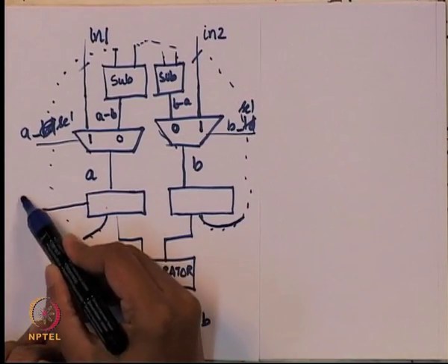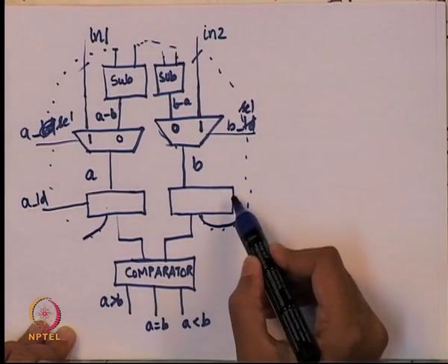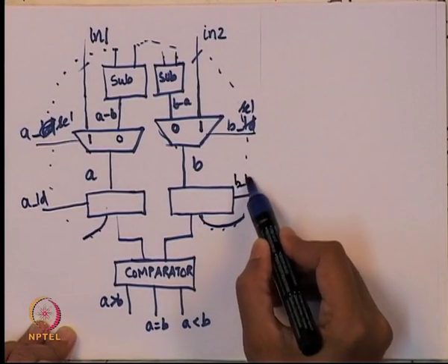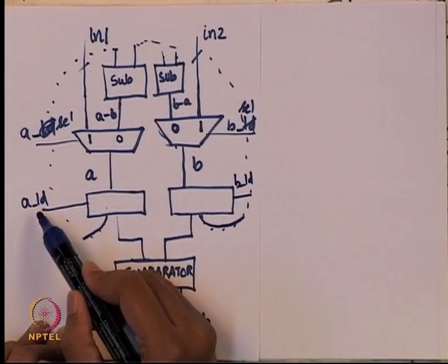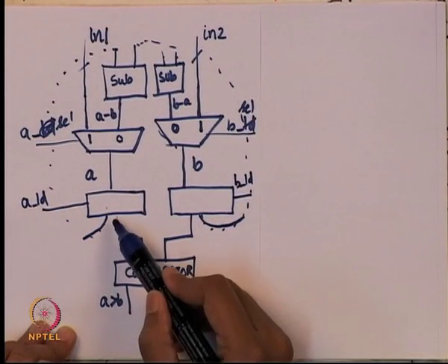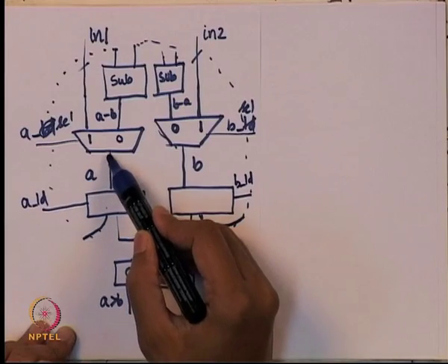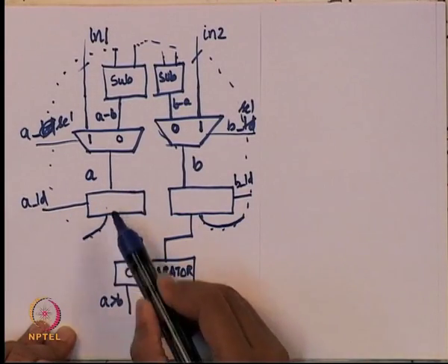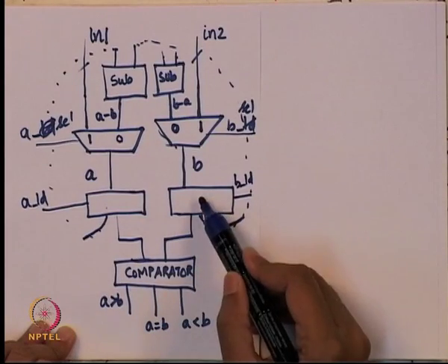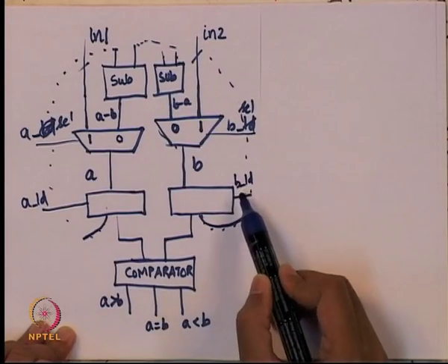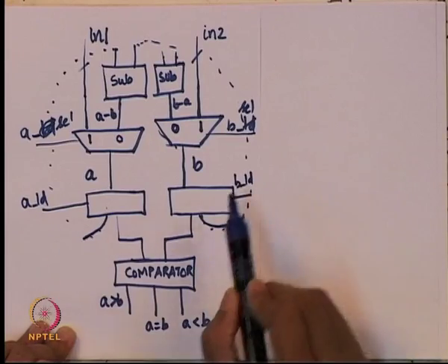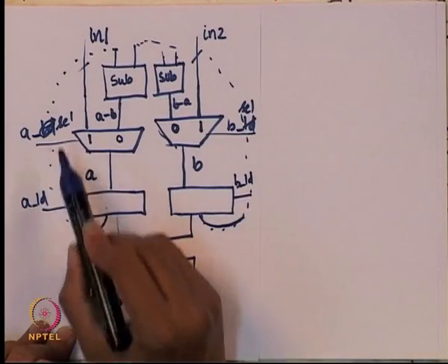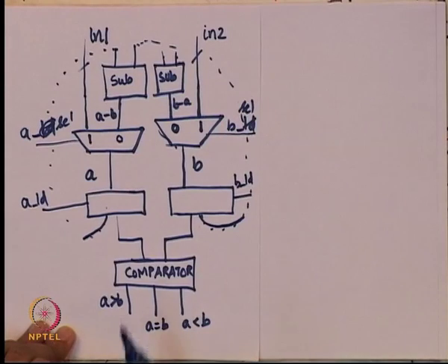So I am going to place some control on the registers on when they get loaded. When A load equals 1, the output of the A register will follow the output of the mux. If A load is equal to 0, then it will keep the old value as it is. The same thing with B. I want to use this underscore load for that signal and select for the multiplexer select. With that small modification, let us see what a data path is.